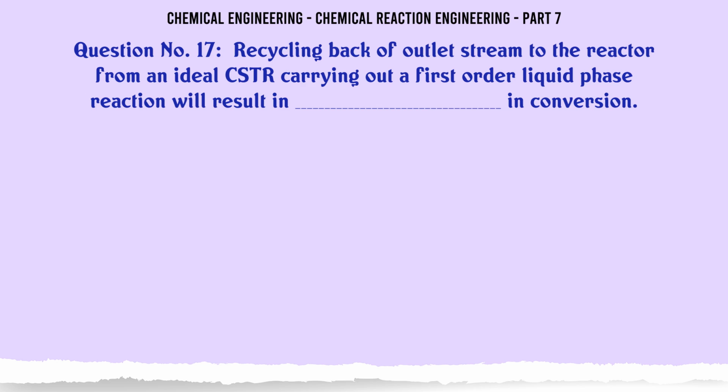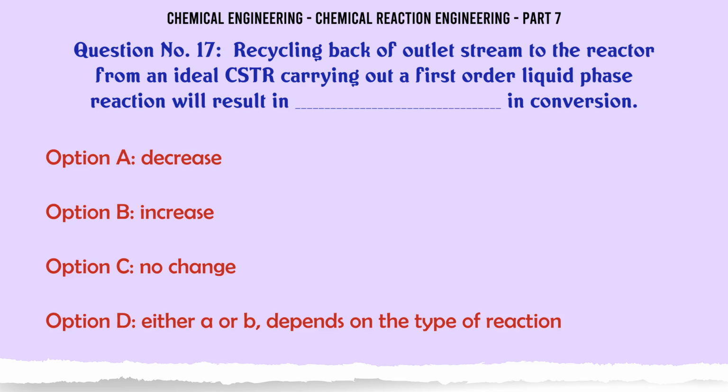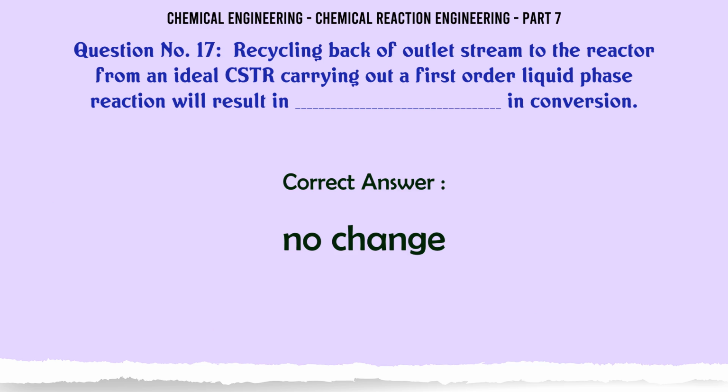Recycling back of outlet stream to the reactor from an ideal CSTR carrying out a first-order liquid phase reaction will result in conversion: A, decrease. B, increase. C, no change. D, either A or B depending on the type of reaction. The correct answer is: no change.